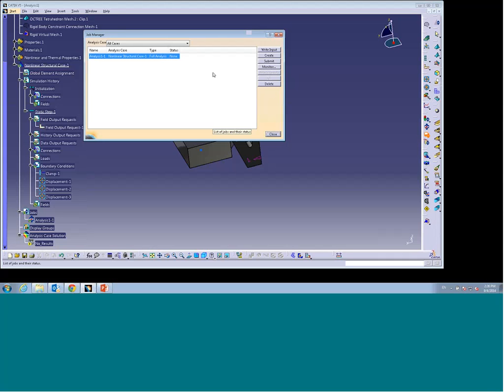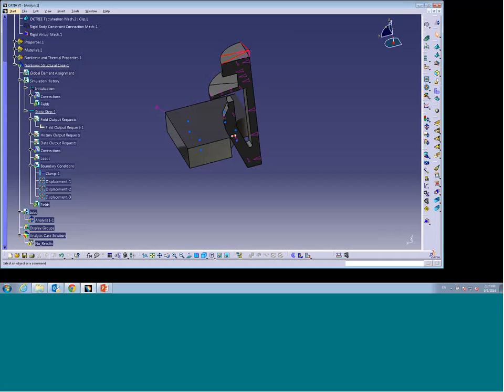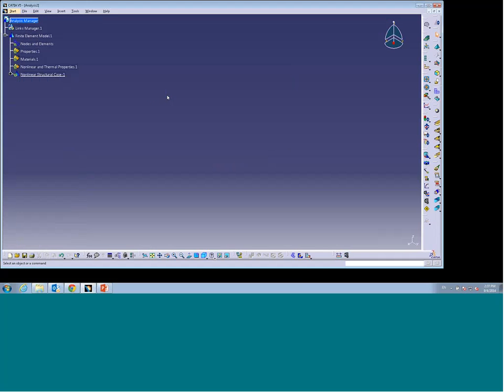I don't want to run this model. It takes about 10 to 12 minutes. We don't have that much time, unfortunately. But in general, as I was saying, you click submit and actually start the job, and we can click at this point monitor and actually observe what's happening. So if we have any convergence issues, if we have any other issues in the model, we would know at this point. So in this model, as I said, I don't want to solve it. What I'm going to do is simply attach the result that I solved before, pre-created before. To do that, I'll just create a new analysis file, analysis document.